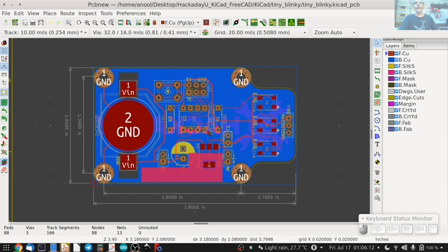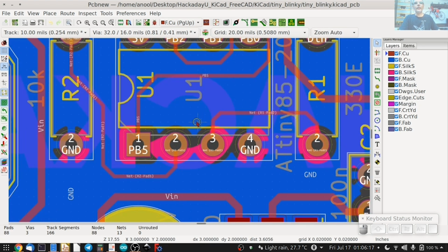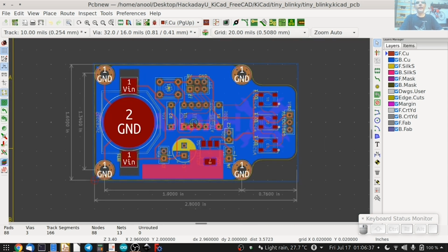The other thing to remember before exporting is to recall that we placed the grid origin offset at the center of the board like so, which, as we noted, was at an XY coordinate of 3 inches by 2 inches. We will use this as the origin for the export of the VRML and the step files.